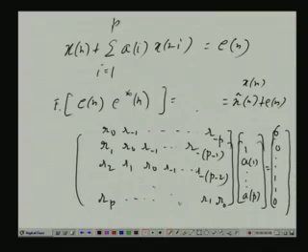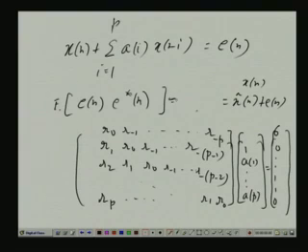This is called forward prediction, because from the past samples we are predicting the future. So, it is a forward direction prediction. So, that is why it is the forward prediction error variance. Sigma square is usually used for variance. So, sigma f square, f for forward. We also put a subscript p to denote that it is a pth order linear prediction or pth order modeling problem. Mind you, this is unknown, because the input E n or the prediction error E n is not known to us, and therefore this is unknown, but still we write it like this. So, how to solve the equation?